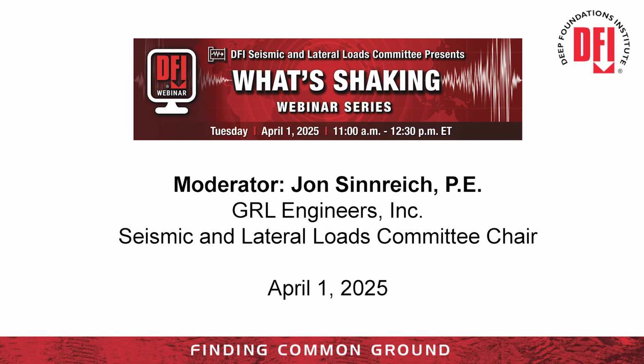The abstract of today's presentation is: soil liquefaction and resulting ground failure due to earthquakes present a significant hazard to infrastructure around the world. On a site-specific basis, liquefaction evaluations are performed by first evaluating whether a given soil material exhibits a type of soil behavior in which large pore pressure generation and strength loss is possible. This is the susceptibility analysis, followed by assessing whether the state of the soil and the potential future ground shaking at the site are likely to lead to such strength loss, the triggering analysis, and finally, by considering the potential consequences if liquefaction were to be triggered.